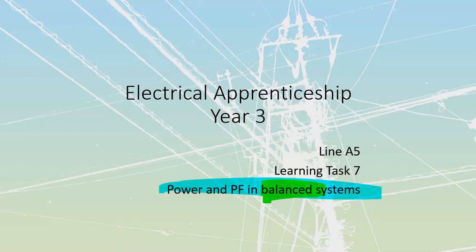First of all, before we do any power factor calculations, we're just going to talk about power itself. You have learned this in second year. Power factor is equal to the cosine of theta, or the cosine of whatever angle we have for our circuit angle. So we've got cos theta, then we can go and figure out our power factor. We can just do that by punching it literally into your calculator with that angle itself. However, if we don't have that phase angle, we have to go and find the rest out through either trigonometry or through something similar to that.